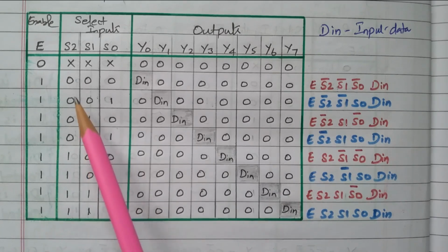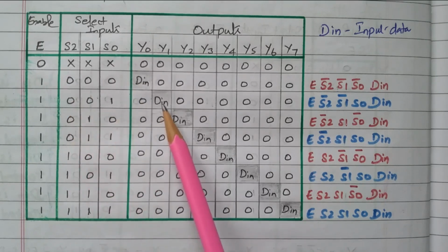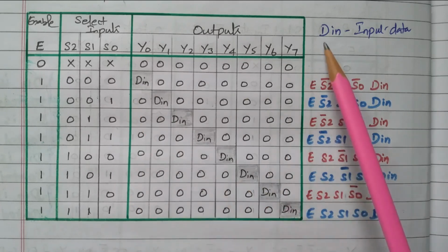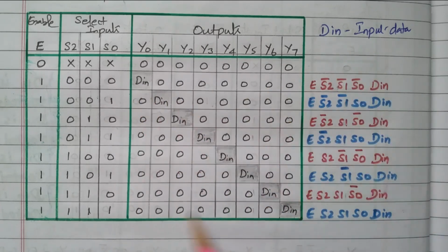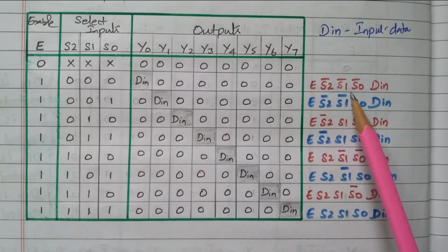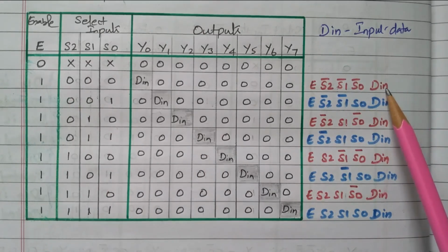Right? So it is very simple. First combination, data available in the first position. Second combination, second position, like that it is available. First position, second, third, fourth, fifth, sixth, seventh and eighth. So that we are getting 8 different outputs. So the single input is now produced as 8 different outputs. But based on the selection line, we are having the complement, so that the data will be high. All the inputs will be high, so that will produce the input at the first position, right?